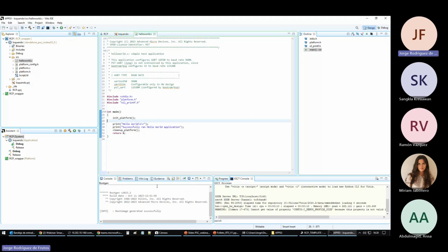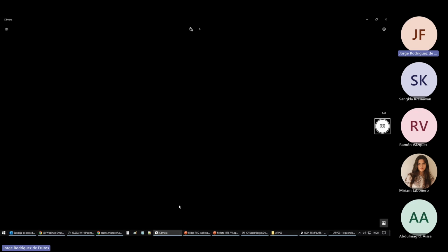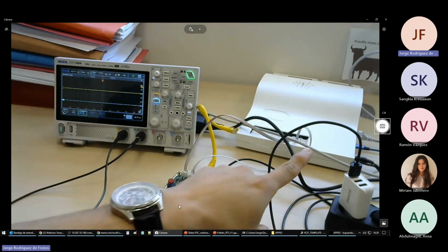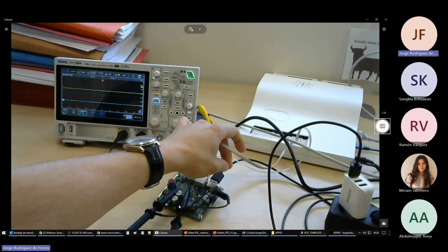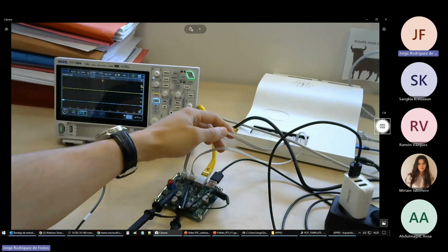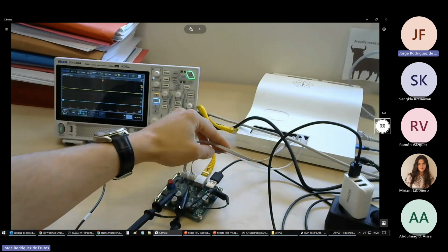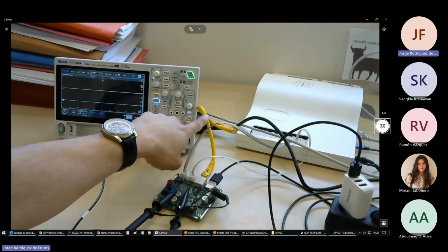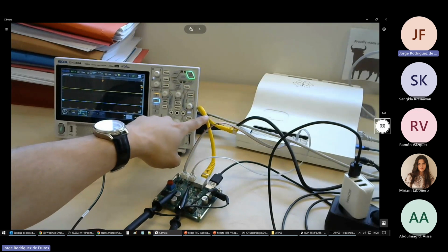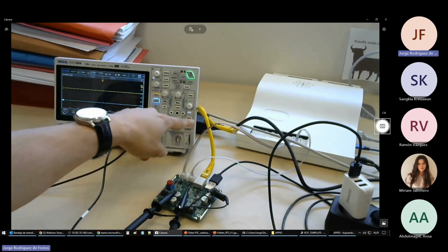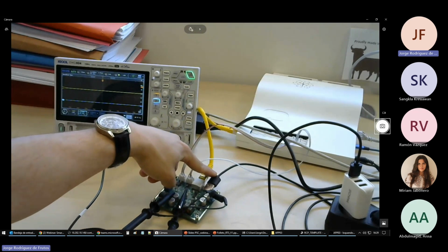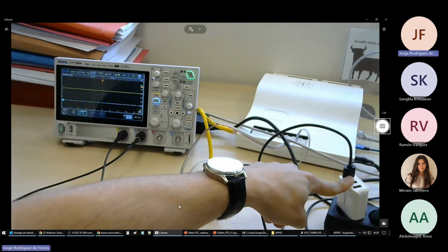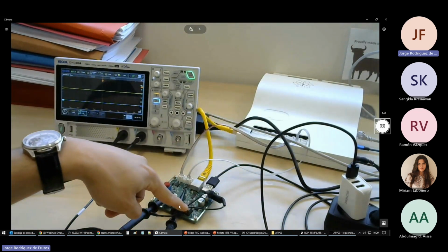I'm going to turn on a camera that I have. So that is the SmartRCP device. Those two wires are for the sensing of the inductor currents and the output voltage. This yellow Ethernet wire is the one that is going to send the PWM signal for the converter. This USB here goes to here and to this power supply. So it is the power supply of this converter.